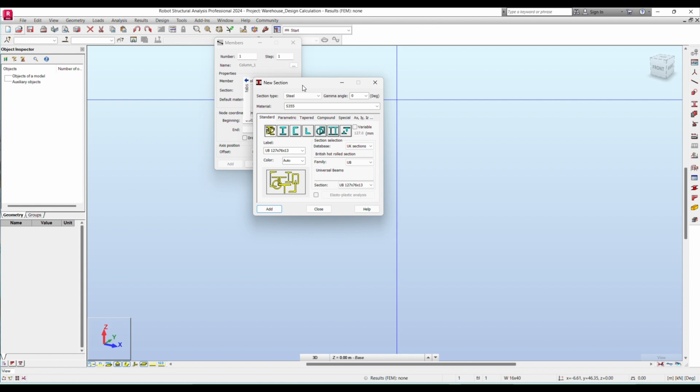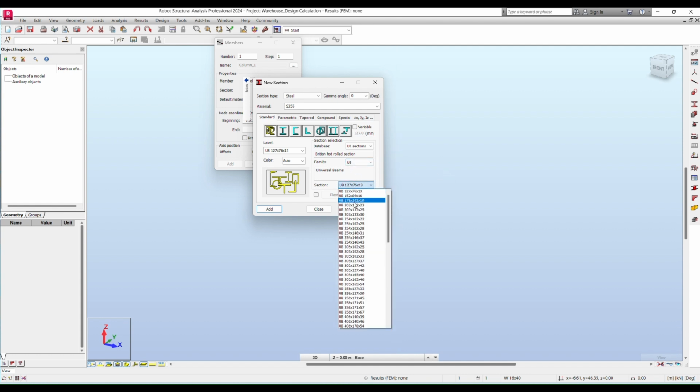Generally this UB will have more stiffness and less deflection compared to the column, but the weight will be higher when compared to the universal column sections. In our case, the warehouse has a 12 meter height with various moving loads also, so it tends to be subject to deflections in the width, length, and depth directions.